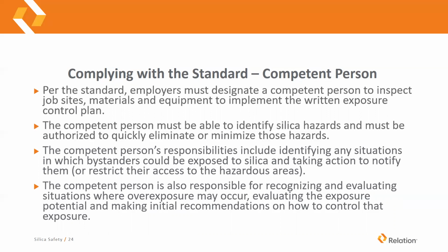you have to protect them. Also, the competent person is responsible for recognizing and evaluating situations where exposures may occur, evaluating the exposure potential, and making initial recommendations on how to control that exposure. So whenever a competent person is being designated, they need to have some knowledge of the hazards of silica, how you're going to control them, and they need to be able to complete and implement the written exposure control plan.